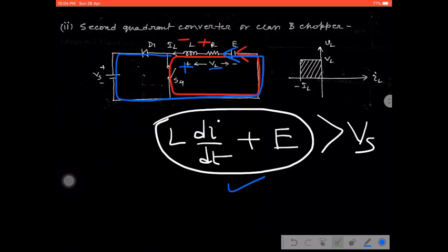That means in the charging path and discharging path, see it very carefully. When the inductor gets charged, the direction was in this direction with respect to reference, that is opposite direction, because we have taken the reference direction of the current as this one. Now the current is flowing in this path. That means opposite direction. That is why current is in the opposite direction. Similarly, we assume the voltage was this one positive and this one negative for the reference. Now due to the presence of the back EMF E, in all the cases the voltage appearing across the load is positive and that is negative.